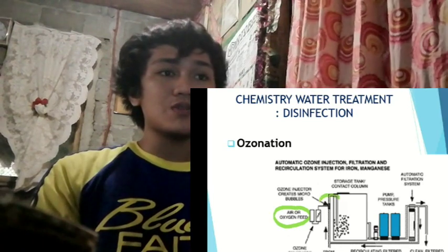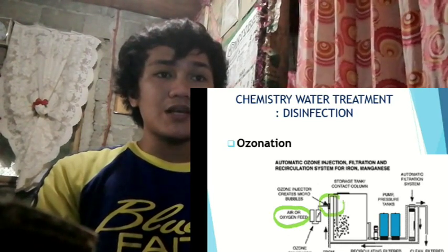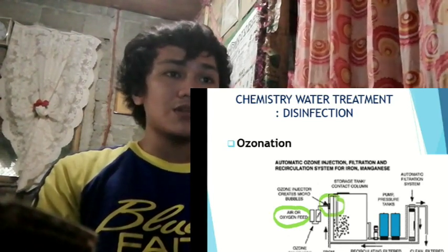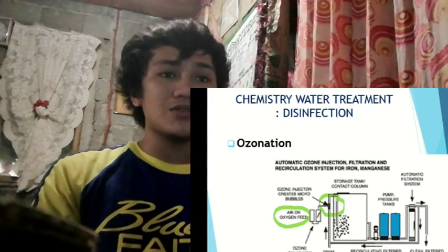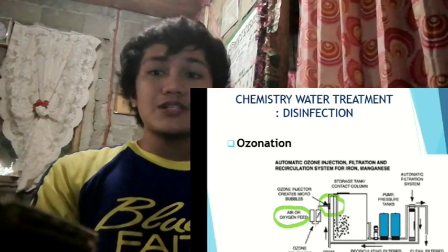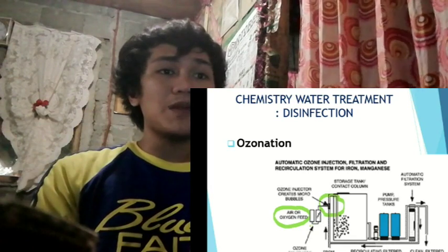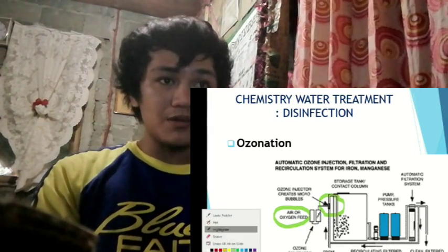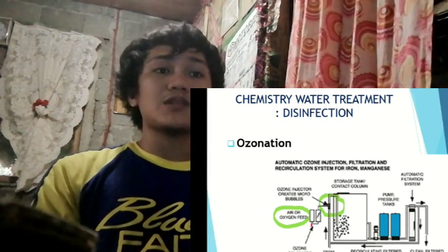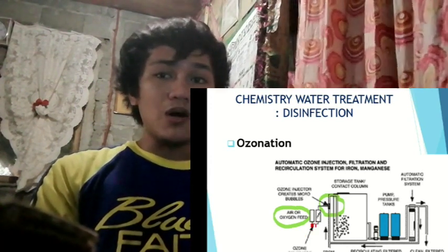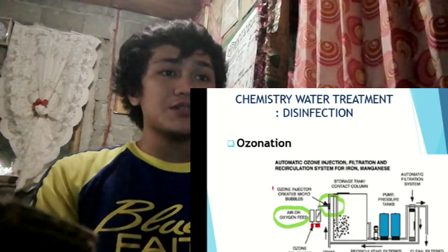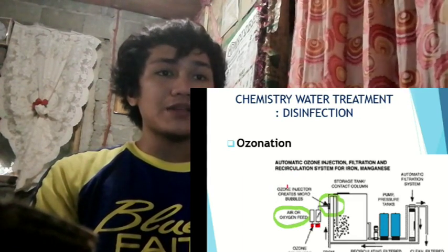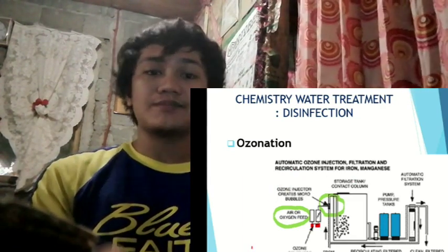To reduce corrosion of generating apparatus, air is passed through a drying process and then into the ozone generator. The generator consists of two plates or a wire and a tube with an electric potential of 15,000 to 20,000 volts. The oxygen in the air is dissociated by the impact of electrons from the discharge electrode.